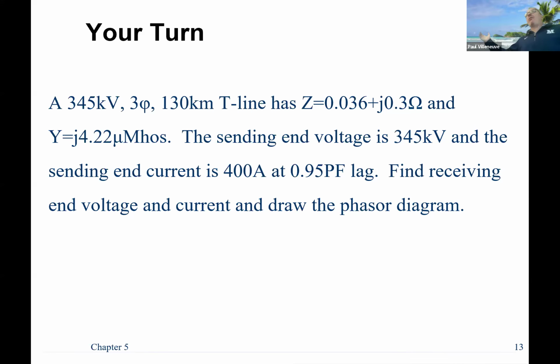Essentially what I'm saying is the power has reverse directions. So what normally is my sending end, now for some reason, the power flows have switched directions. Maybe, if we're in Maine here, maybe New Brunswick had a problem and they opened up the 345 kV tie lines. So all that power that used to come in through New Brunswick and then head down south now has to go in the opposite direction. Now we need backfeeding power to go that way.